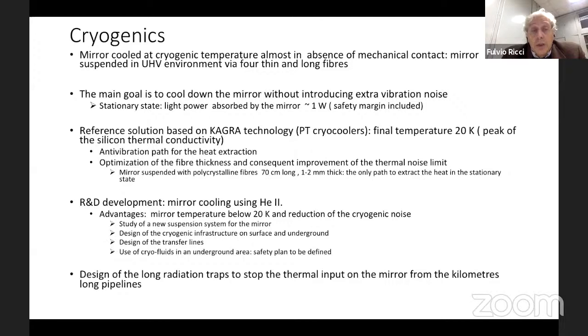And we need to ensure that the cool down is done with a refrigeration power that permits to extract the residual heat absorbed by the mirror, which is in part due to the residual thermal input in the cryostat, and a relevant fraction of this heat comes from the absorption of the light that is pumped into the interferometer.